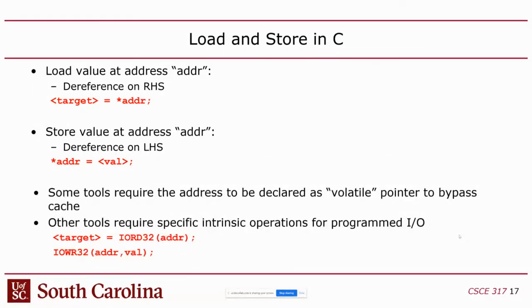Now the problem with this is that if you do this, you have to make sure that these loads and stores are bypassing the cache, because you're assuming that these loads and stores are translating directly into communication events between the CPU and the target peripheral. And that's a bit of an issue. The way that works is actually specific to whatever processor you're targeting.